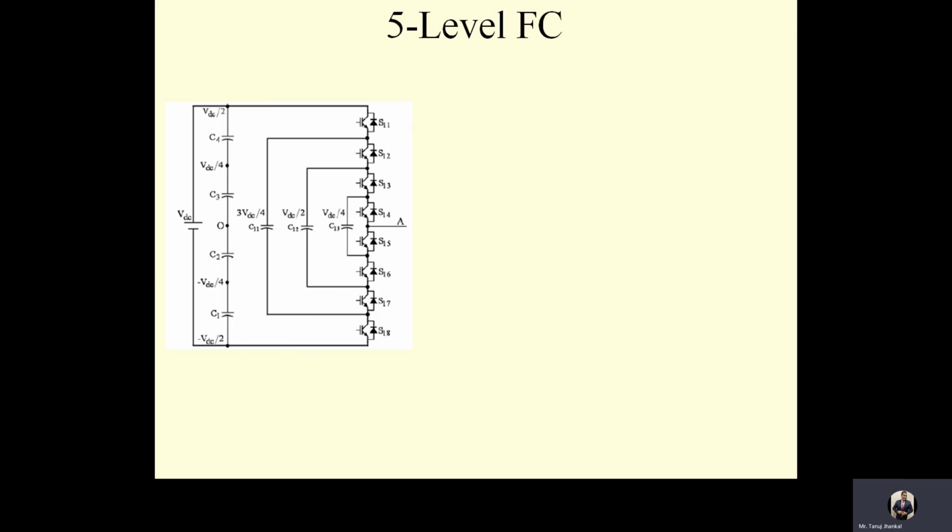This is achieved by proper selection of the switching combinations to impose equal duty ratio in the respective switches. Hence, the control strategy employed in flying capacitor based multi-level inverters should be able to maintain the capacitor voltage in addition to the required control action.